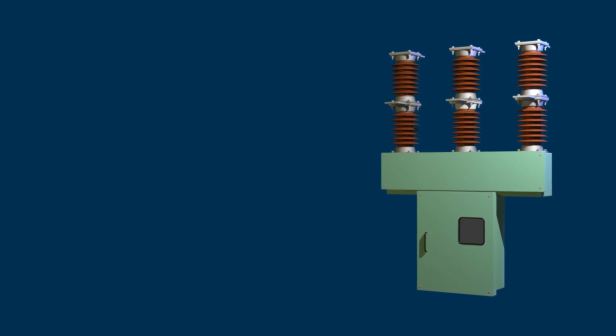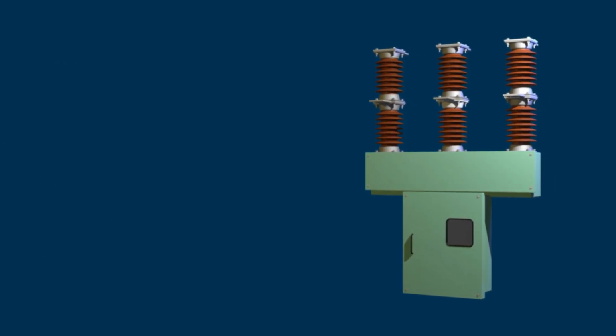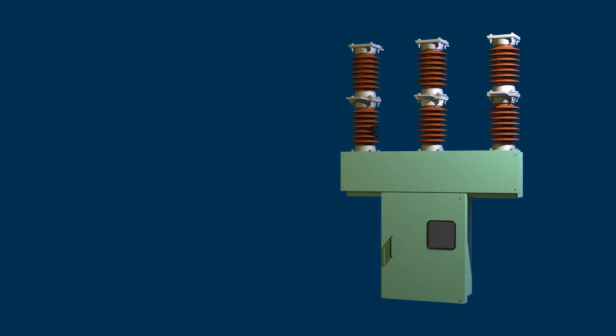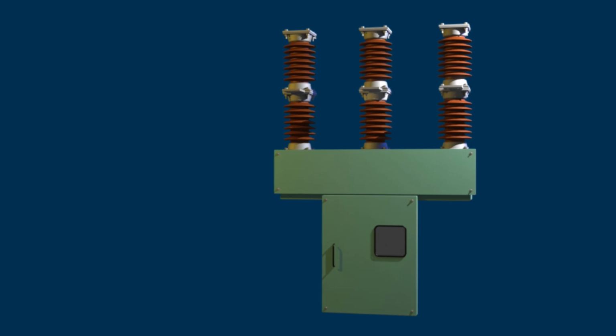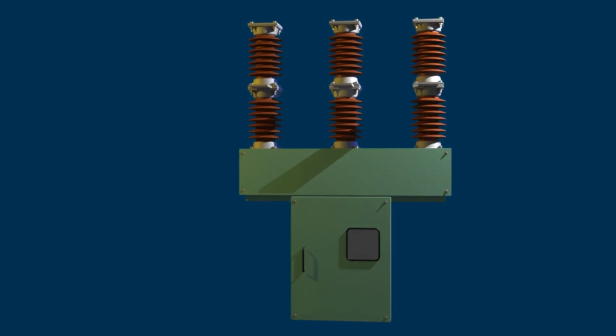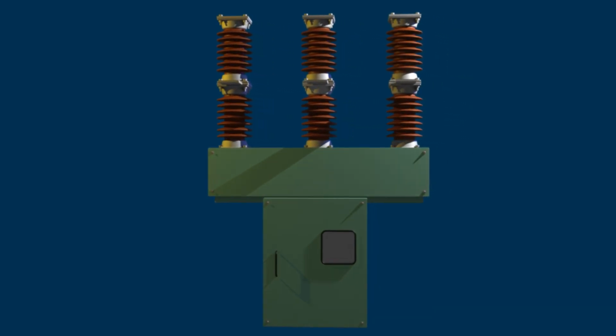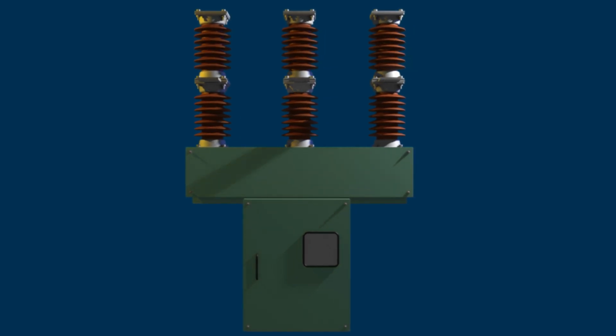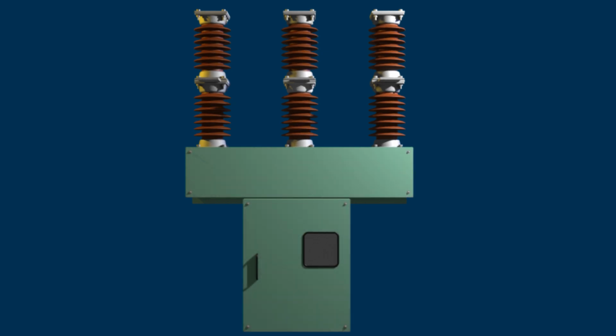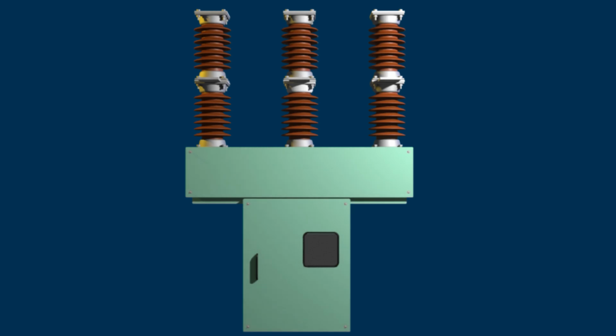of vacuum circuit breakers. A vacuum interrupter, which we also call a VI for short, is the key component of a vacuum circuit breaker or VCB. In a vacuum circuit breaker, the arc quenching takes place in a vacuum. No medium like air, oil, or sulfur hexafluoride gas is used for this purpose. In a vacuum, there is no medium present. Hence, no ionized particles in the gap between the breaker contacts.